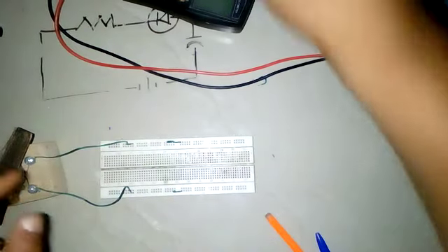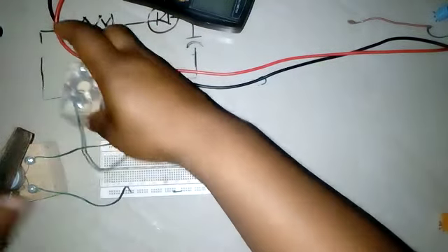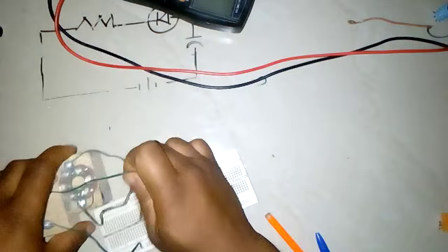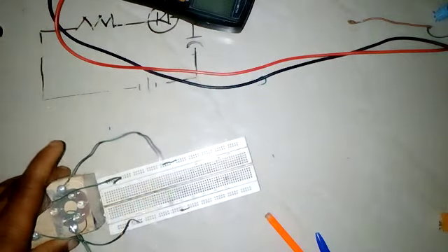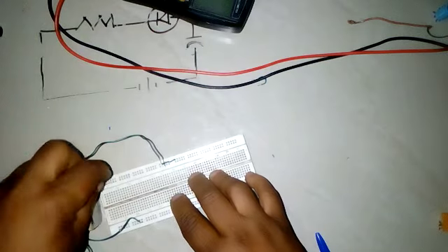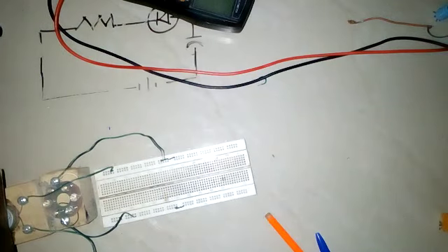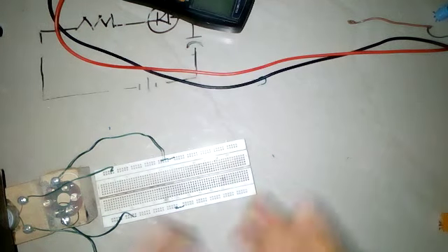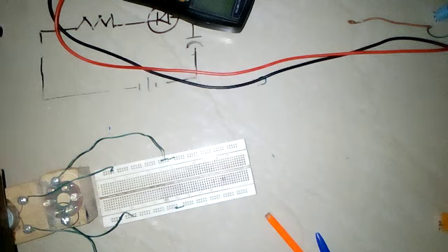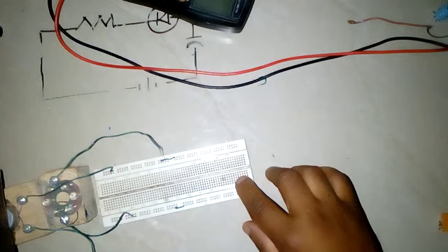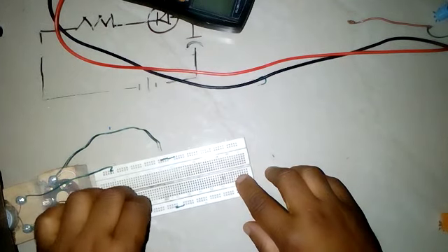And this is the LED set we used. I'm putting it here. So let's put this one here. Okay. Now I did mention that these two devices are connected in parallel. What it means is that the negative terminal of the DC motor was tied to the negative terminal of the LED set, while the positive terminal of the DC motor was tied to the positive terminal of the LED set. My apologies. This way.